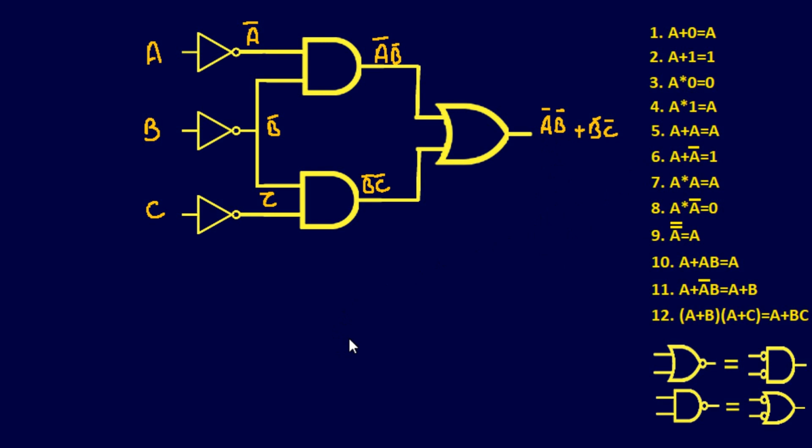So let's do our same method and see if we can actually find the equivalent output of NOR gates. I want to create not AND gates, so I want to actually create bubbles here and here. So if I do that, I'll create a bubble down here too. So that would actually create an OR gate right here, and then an OR gate right here. The great thing about OR gates and NAND gates, anytime you want to create an inverter, you just short the inputs. Let's see if I can draw them similar. So right now, if you use both of these and actually short the inputs, you create an inverter.